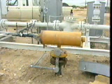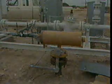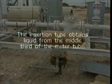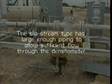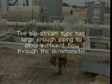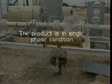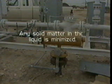The accuracy of densitometers is dependent on several factors. These factors include that the insertion type obtains liquid that is from the middle third of the meter tube, that the slipstream type has large enough piping to allow sufficient flow through the densitometer, that the product is in single-phase condition, and that any solid matter in the liquid is minimized.